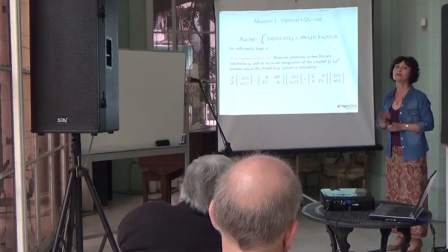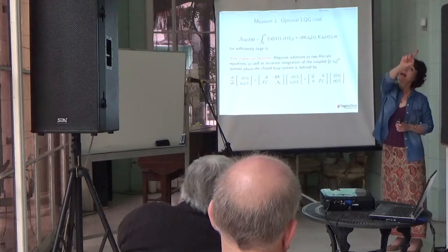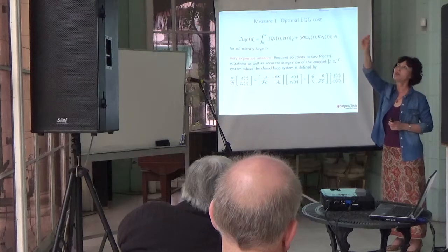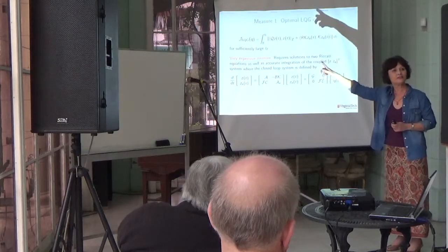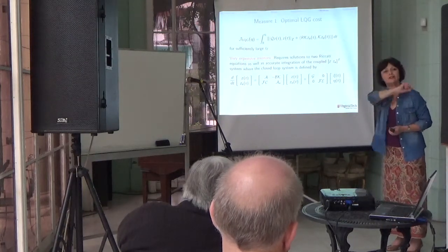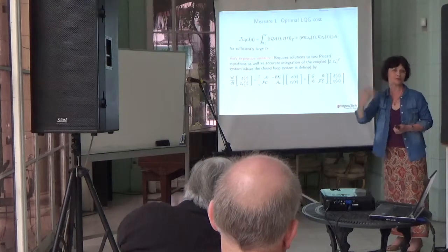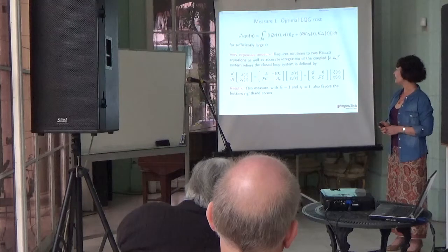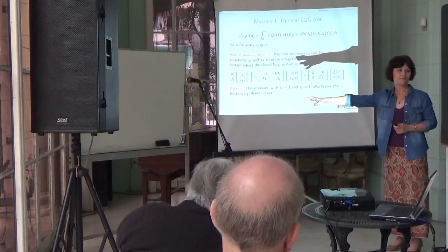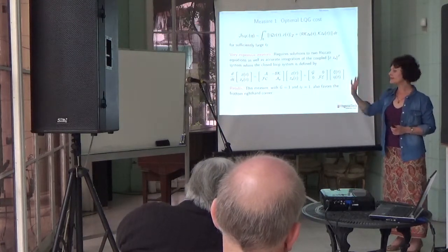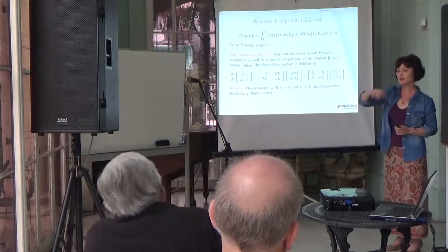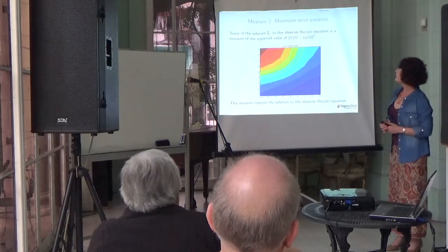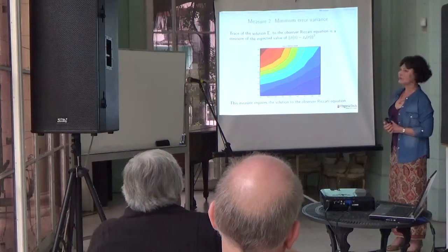So what we did was we took this wall, and depending on the nodes of the Taylor-Hood elements, we had 225 locations for the sensor, and just brute force calculated for each sensor location to see what was optimal. There wasn't an optimization on that. And it favored the bottom right-hand corner. So this measure, even though very expensive, indicated that if in this framework we have to place a sensor, we will do it in 5.